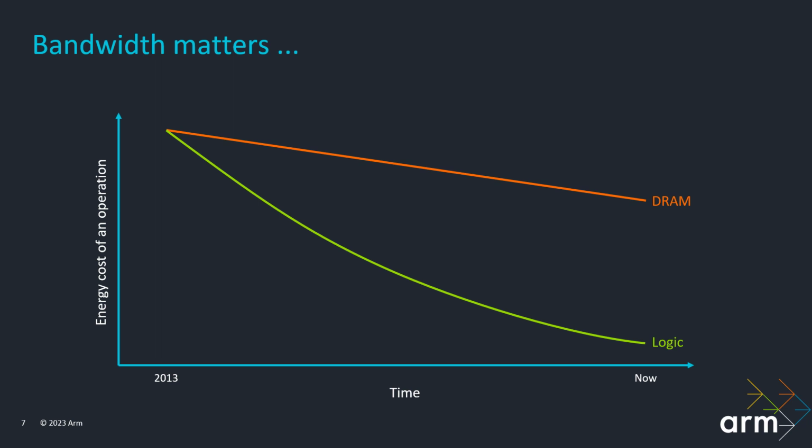So a lot of the best practice we talk about is about trying to reduce the amount of memory traffic that your application is generating. As you can see here, this is becoming more important over time. Memory is taking up proportionally more and more of that power budget. And we are seeing games now where more power is being spent on DRAM than is being spent on the GPU itself with the latest ARM GPUs.